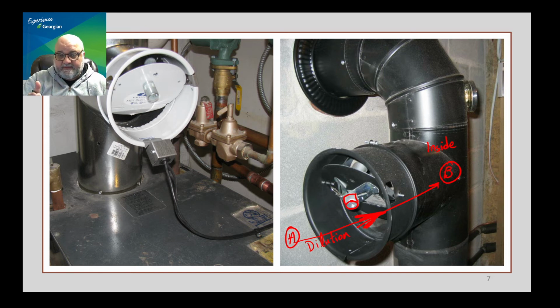As we have seen before, there are two possibilities to make this a desirable option. One is if there is a blockage where the combustion products cannot go through the venting system to the atmosphere, you don't want it to build up in the appliance and the venting system. You want it to spill outside.